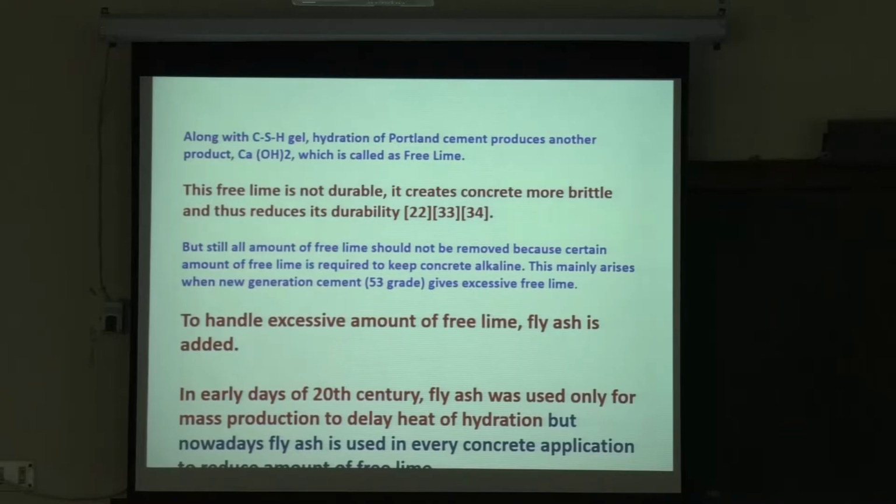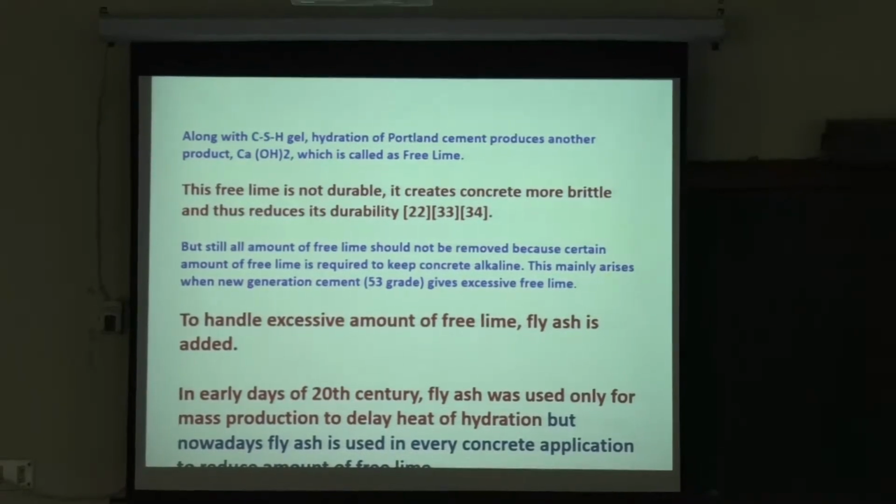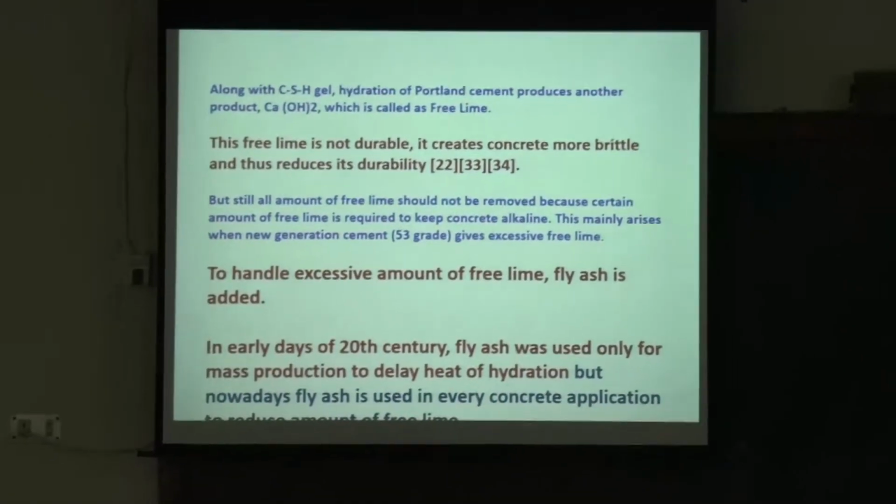Is the volume of two components always the same? No. If the composition changes, that means the material changes from one chemistry to another, and the volume may change. If the volume goes up, it will put compression. If the volume goes down, it might cause tension.